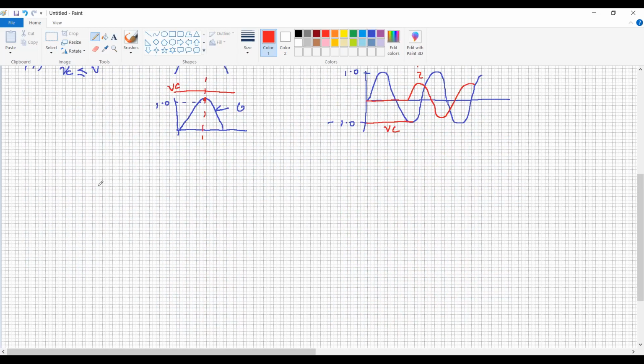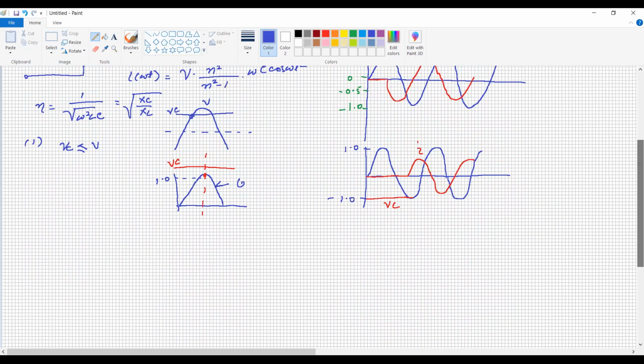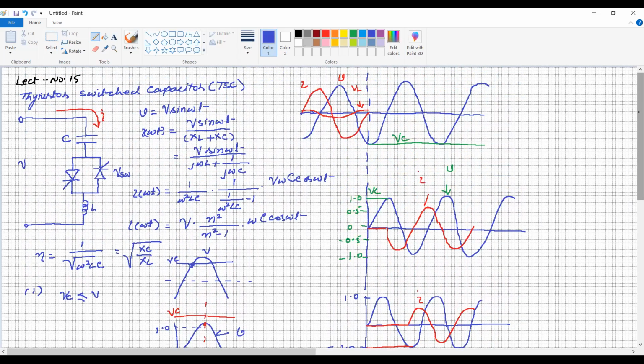What we will do, we will take some other example when the capacitor is fully discharged. The meaning is that whenever we are handling any type of capacitors in the power system, or somewhere where the capacitors are connected in the machines, or somewhere in the circuit, it is advised that the capacitor should be discharged before handling it. For example, someone is disconnecting our single phase capacitor start motor, so it is better to discharge the capacitor.